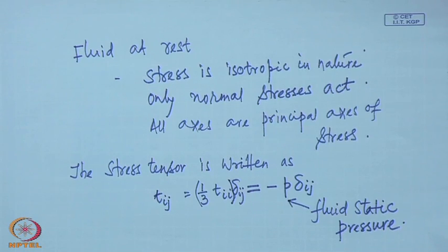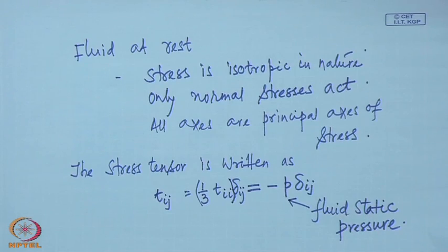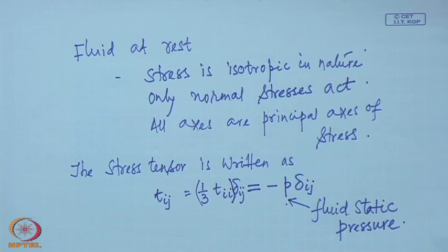Perhaps the word hydrostatic pressure is more familiar to you, because water was perhaps the fluid studied most, and pressure and all these things were usually encountered with water. So, since long this pressure is referred to as hydrostatic pressure, but we are making it more general, fluid static pressure. So, this is the definition then of static fluid pressure, that it is 1/3 of the sum of the normal stresses acting on a fluid at rest.